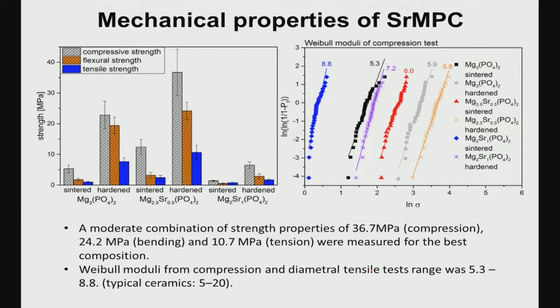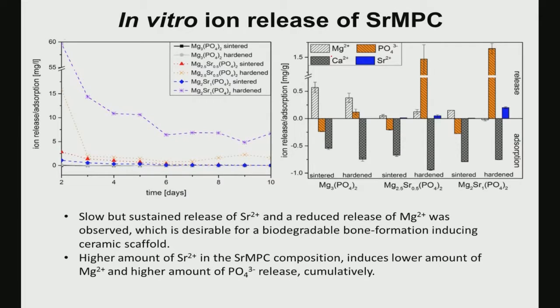In terms of the mechanical properties, you can do a lot of other interesting things, and that is called Weibull modulus. Weibull modulus means strength reliability, and you can see the strength reliability values, that is the m values. M is the Weibull modulus, it is around 9 or 5. These values are very important because additive manufacturing is one of the newer techniques. So, here it is important to define the strength reliability of ceramics, which is a major concern for other conventionally sintered materials.